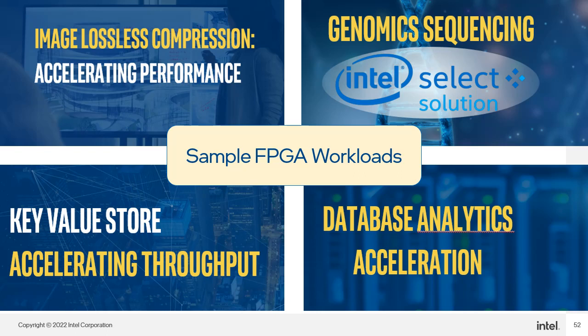Another kind of algorithm that FPGAs are good at are those that take advantage of the customized memory structure that is built. For example, compression has a lot of carry loop dependencies because of the large data that comes in. In compression, you are looking to compare new data to current data, requiring a sort of looping through more and more values as you continue comparing it to lots of different data. As many values as you can grab from the memory at one time, you can do comparison for. Hence, taking advantage of the memory structure of FPGAs, you can achieve this in a good time. This type of algorithm is difficult to express in a parallel type program, hence GPUs will find it difficult to execute.